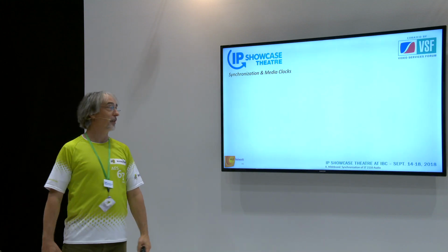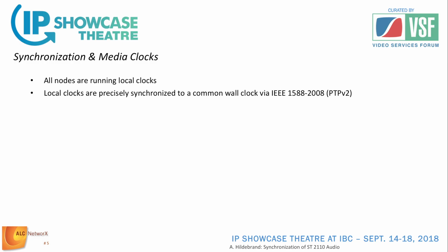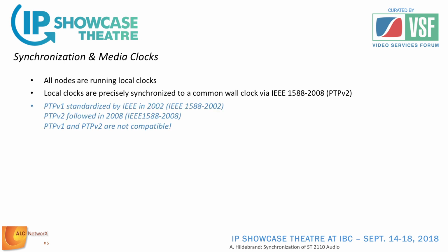How do we achieve this? Well, all nodes have to run local clocks. We know that by now. These clocks need to precisely synchronize to a common wall clock, and we use Precision Time Protocol 1588 in the PTP version 2. Remember, there is a PTP version 1 standard out there, and it's also being used by some gear, but we need to use PTP version 2 because that's what we all settled on for AES67 and 70, and these two versions, unfortunately, are not compatible.